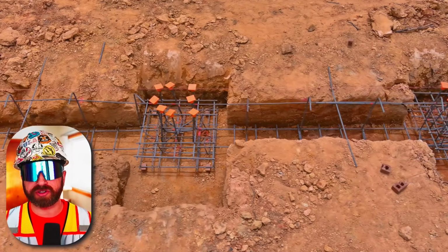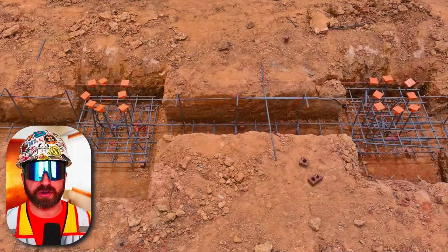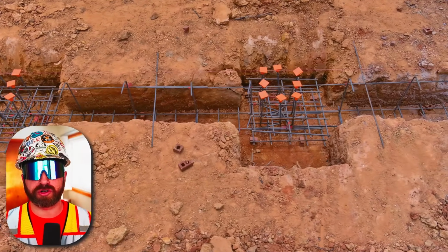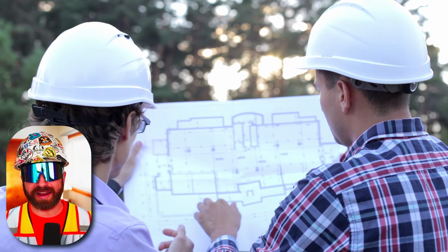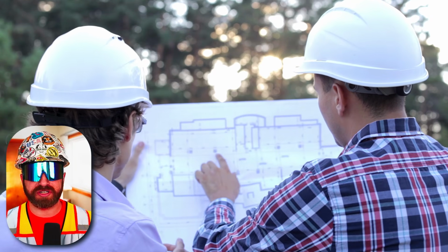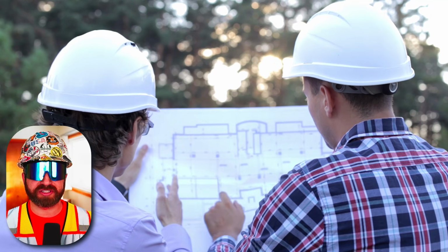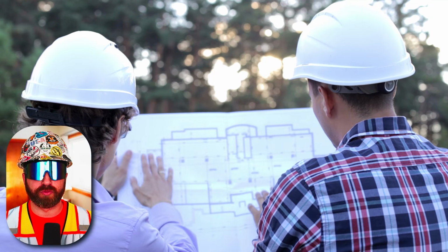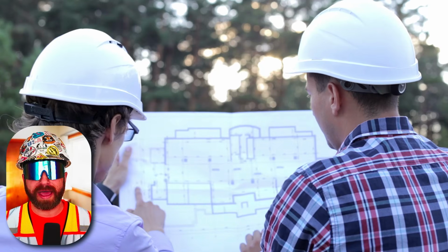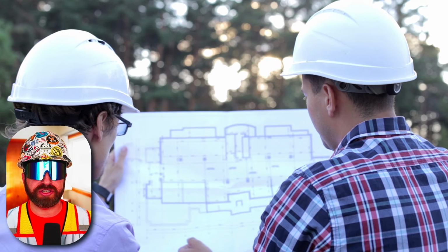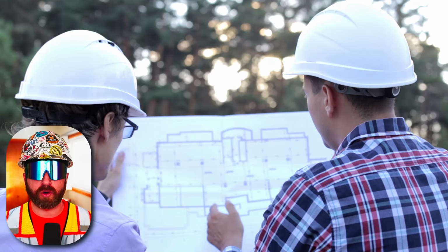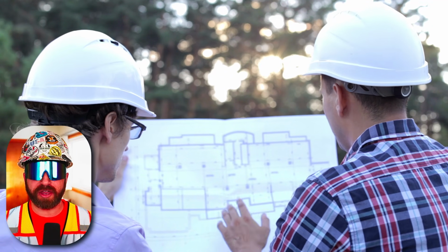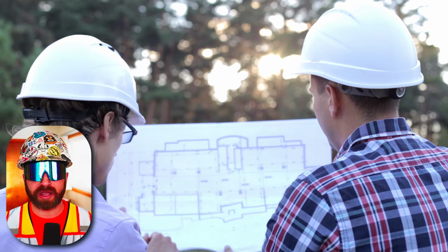So the installing concrete contractor either has an individual who prepares these rebar shop drawings in-house, or more commonly, they hire another company to complete them. Rebar providers who furnish the rebar typically offer this design service. The individual who produces the rebar shop drawings would also have a structural engineering degree. This rebar designer reviews the structural set of construction documents, takes a look at the rebar size, spacing, location, quantity, and layout to produce their own set of rebar drawings for submission back to the structural engineer. The structural engineer reviews the rebar drawings for conformance with the construction documents that they produce, ideally stamps them as approved, and then you're able to release your rebar into fabrication.